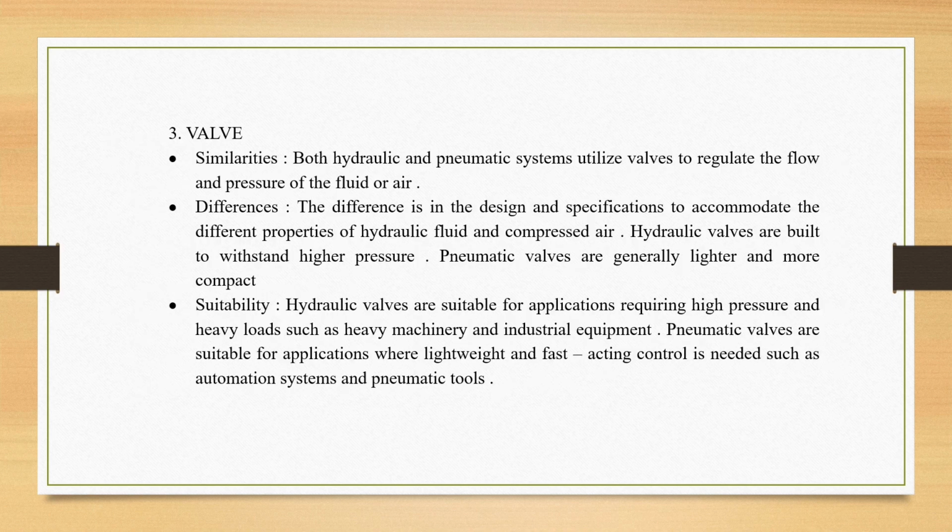Next are valves. The similarity is that both hydraulic and pneumatic systems utilize valves to regulate the flow and pressure of the fluid or air. The difference is the design and specification to accommodate the different properties of hydraulic fluid and compressed air. Hydraulic valves are built to withstand higher pressure.